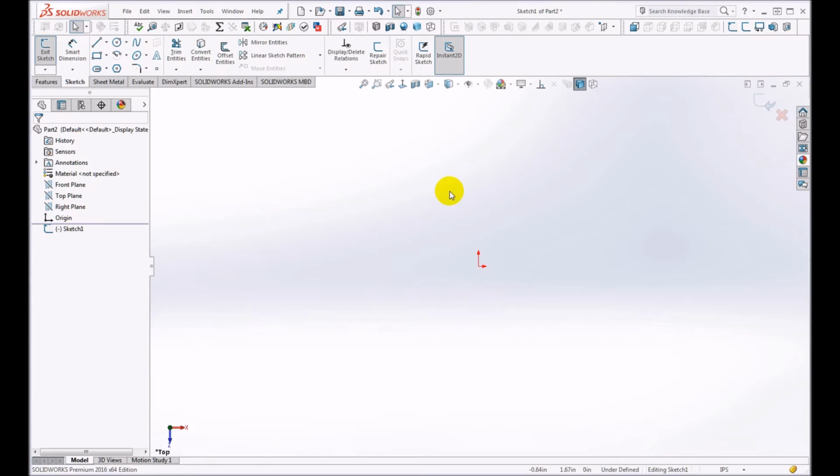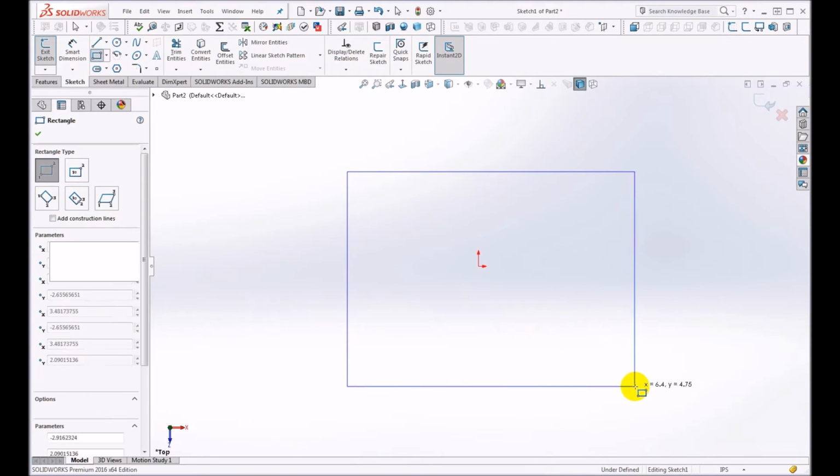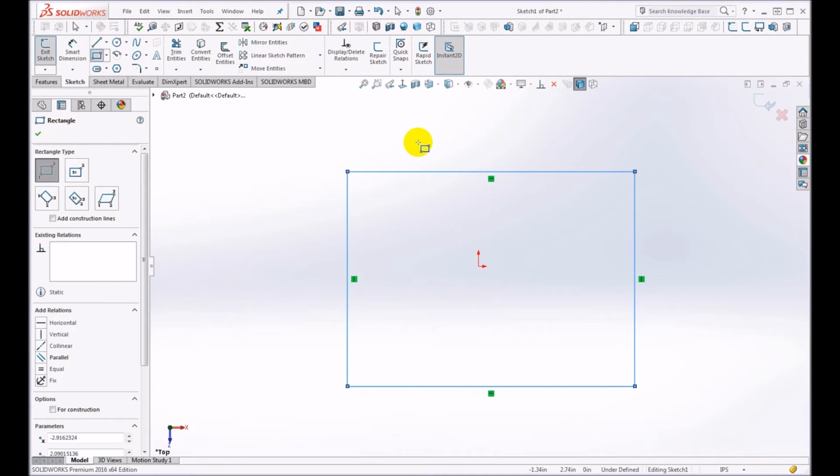So I'm going to go ahead. The exercise asks us to find the rectangle tool. It's up here. It should say Corner Rectangle. If it says any other kind of rectangle, click the down triangle and pick Corner Rectangle. Now we're ready to draw a simple rectangle. Using the left mouse button, I move out into my work area, click the left mouse button, drag down, and release. So now I've created a rectangle, and I can accept it by closing the rectangle dialog, or I can press the Escape key.